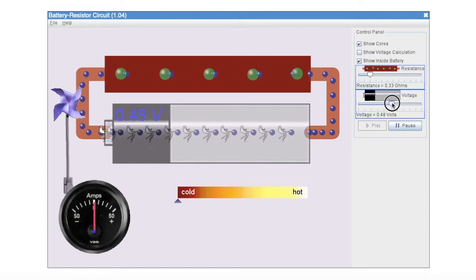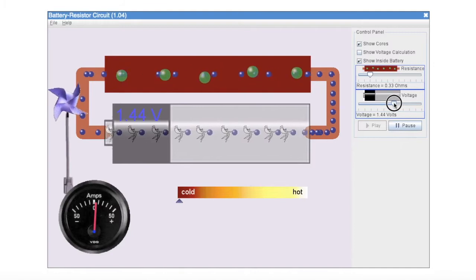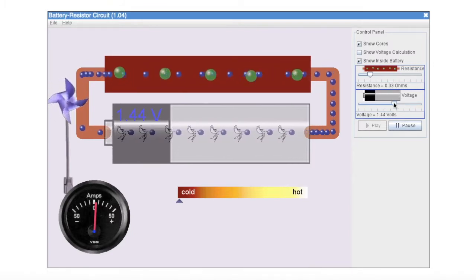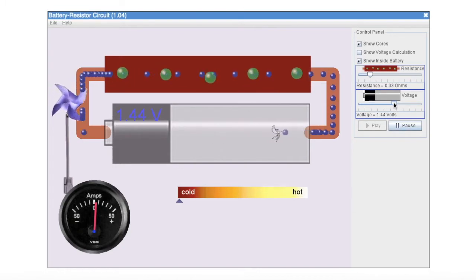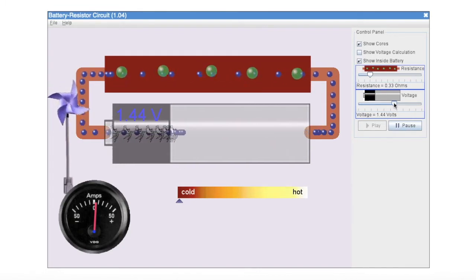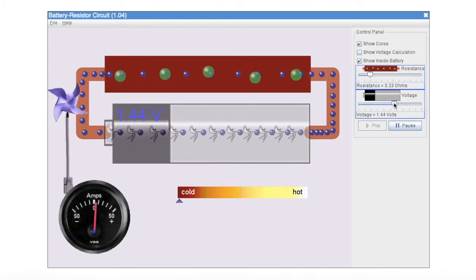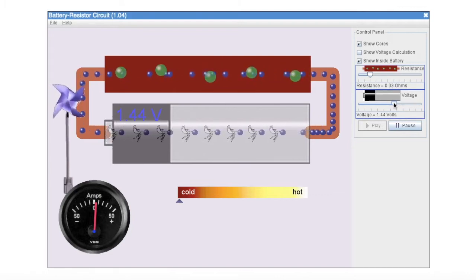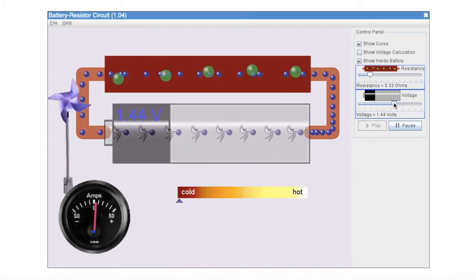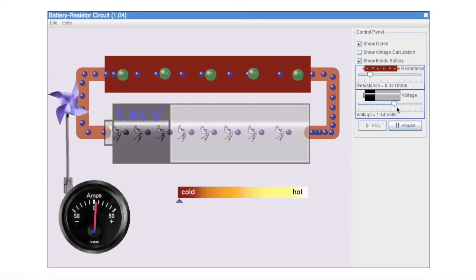Then, as we started to increment the voltage applied, we are seeing much more rapid vibrations and at a higher amplitude for the atoms, which is an indication that the energy being lost by the electrons and absorbed by that conductor is being supplied to the atoms in terms of kinetic energy. So each atom is gaining speed, vibrating at a much higher amplitude and more rapidly.